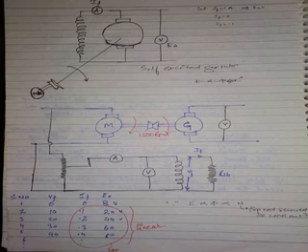Any machine, the core is designed to operate for a particular flux density value. So generally, the preferred operating region is this knee point region. After this knee point, OCC gets saturated. This is before saturation, this is after saturation.